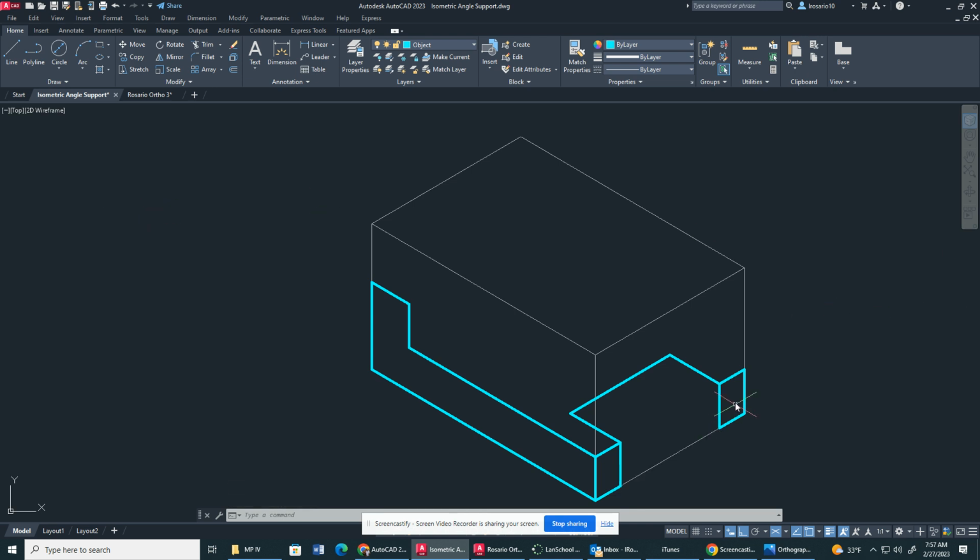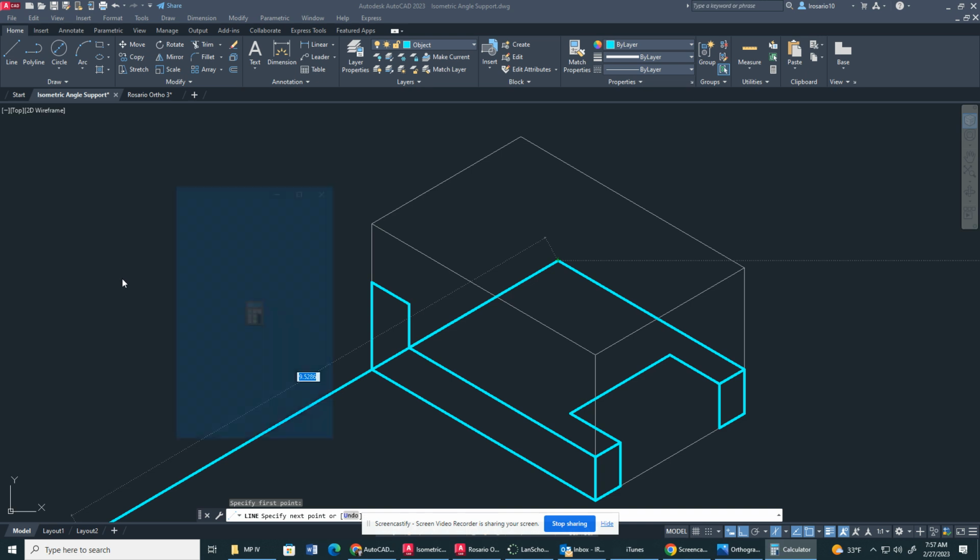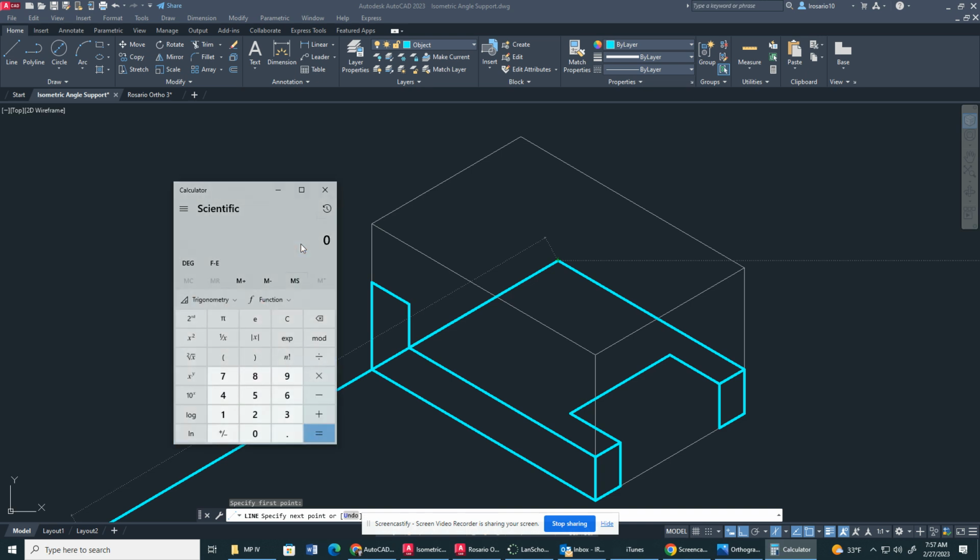Now, what I'm going to do next is I'm going to go across or up by 3.75. Finish this line right here. Press F5 again. Change my plane. I'm going to go up right here. This is going to be 2.5 minus 0.75. I feel like doing math at this moment.